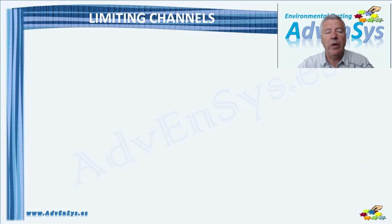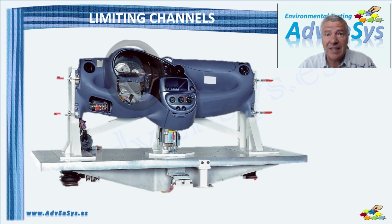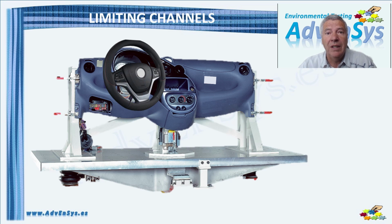Let's imagine we want to evaluate the vibration response and find resonances of a new DUT, for example, a steering wheel prototype. We will test at a relatively low level, but we know that the maximum acceleration on a particular part of the DUT can by no means be higher than a certain level, or the prototype will irreversibly get damaged. We don't expect those high levels, but the response is unknown. Therefore, we better decide to protect the DUT with a limiting channel.